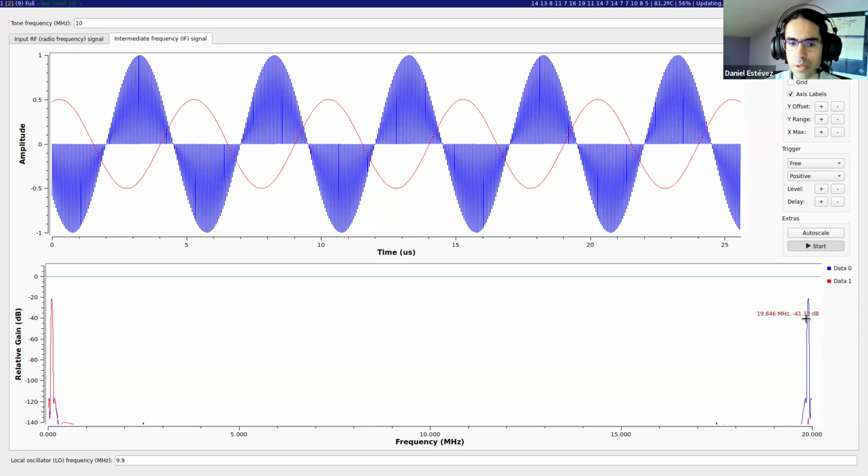And then my signal would become absolute garbage because I would have superposition of two FM stations. And if one of them is stronger than the other, maybe you might hear the stronger station, that is called the capture effect, which is quite specific to FM. But in general, you would hear noise or something very garbled.